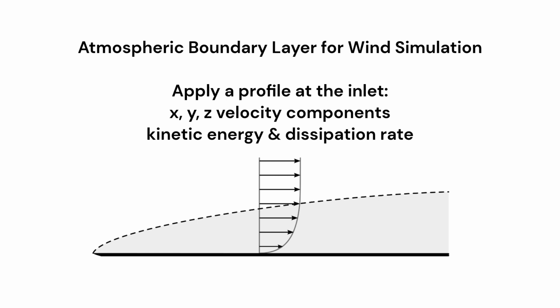In this model, we want to establish an atmospheric boundary layer to simulate wind. Our profile consists of XYZ velocity components and turbulence values for kinetic energy and dissipation rate.